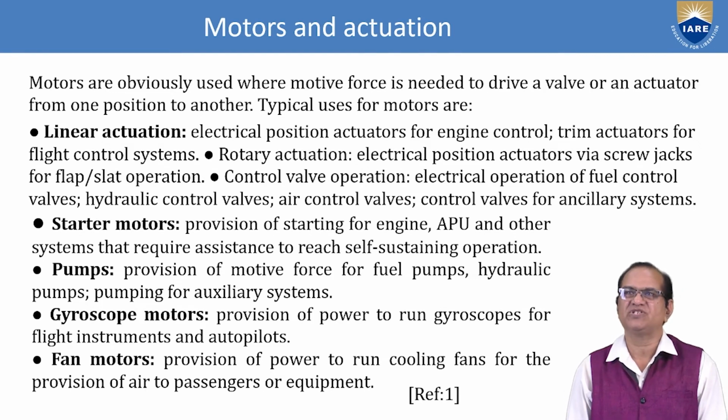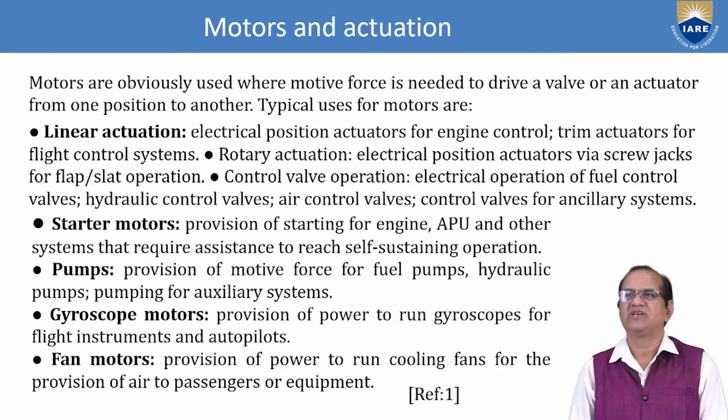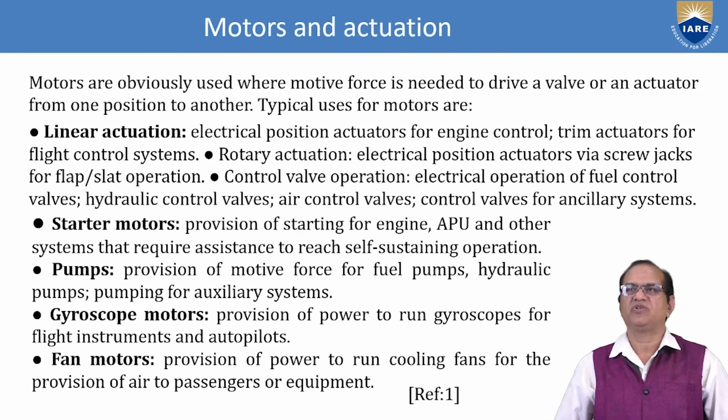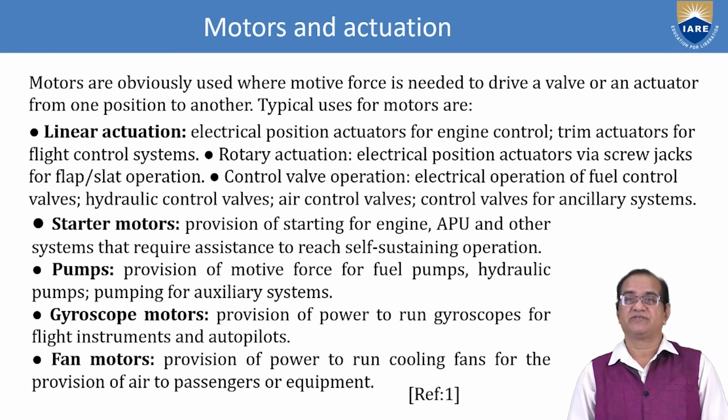These are electrical position actuators for engine control, trim actuators for the flight control system, and rotary actuation, electrical position actuation via screw jacks for flap and slat operations. Control valve operation: electrical operation of fuel control valves, hydraulic control valves, air control valves for ancillary systems. Starter motors: provisions of starting for engine, APU and other systems that require assistance to reach self-sustained operation. We also use some pumps.